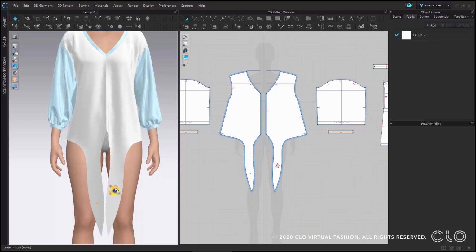You can do so by right-clicking on one of your pins, and you find two commands: delete selected pin or delete all pins. There is an even easier way: if you press Ctrl and W, you delete all pins by shortcut.